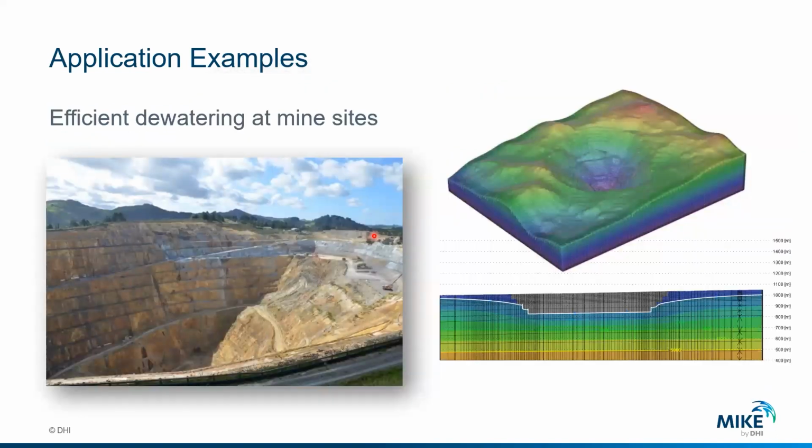Or other cases of mining applications, if you see infiltration processes, so you see the walls of the pit mine or the pit shell, there will be infiltration. Maybe there are some drainages, maybe you have some recharge on top which is infiltrating, so you would like to model these processes in the unsaturated zone in order to better estimate your pressure distributions or the seepage calculations.